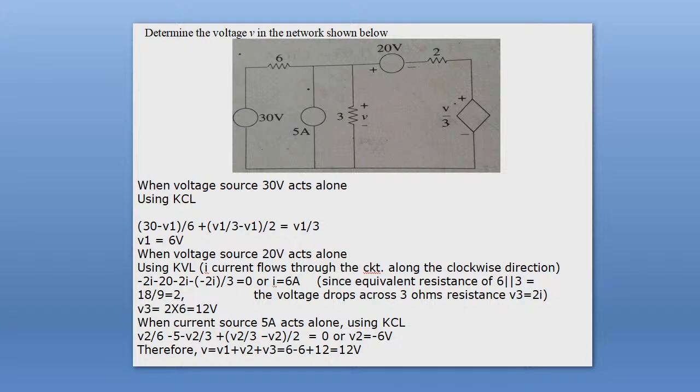Everyone remember this one thing, keep in your mind that to solve a circuit theory problem with dependent sources, you need to consider them in each and every case when you consider independent sources individually. When you consider independent sources individually, that time you must consider dependent sources along with independent sources.